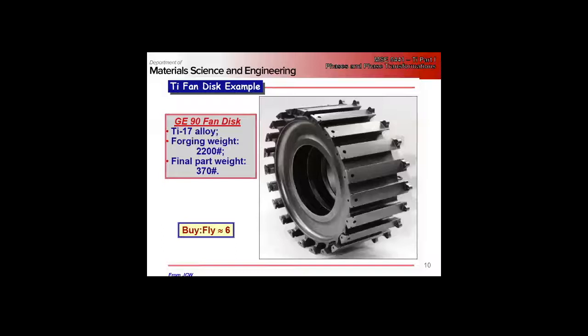But to get there, we have to start with a forging that's over a ton, right? So we start with 2,200 pounds of material, forge it, cut away the outer surface stuff, then machine this part out, right? So we're actually processing 6 pounds of high-grade material for every 1 pound that actually ends up in your component. And the rest of this has to go back through scrap and recycling, right? So this sort of highlights a major issue with titanium, and that's sort of the life cycle method, right? How do we take care of that?